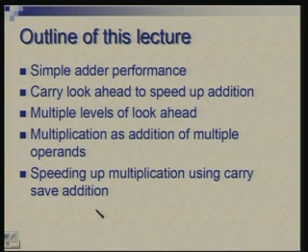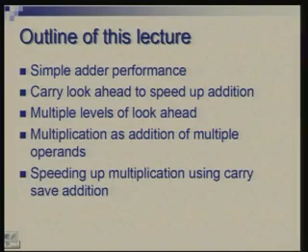First, we will look at a simple adder which we have discussed and see what actually governs the performance, what the bottleneck is. We will see a technique which is called carry look ahead. We will notice that it is the carry which is taking time, and some way to compute the carry fast is what is required. Then we will go over to multiplication, and try to see how multiplication can be carried out in a fast manner.